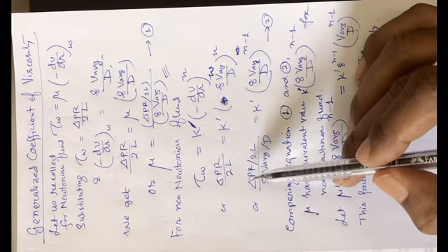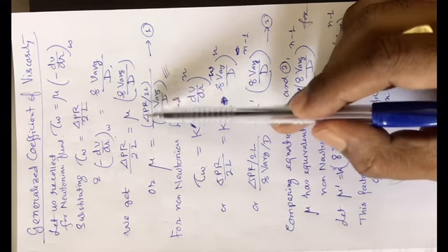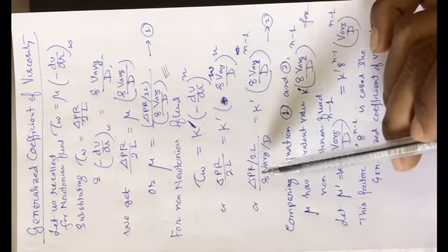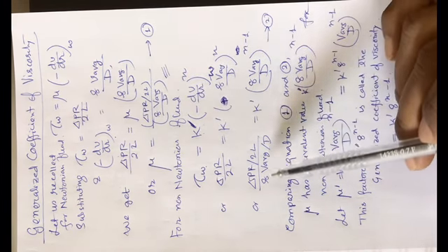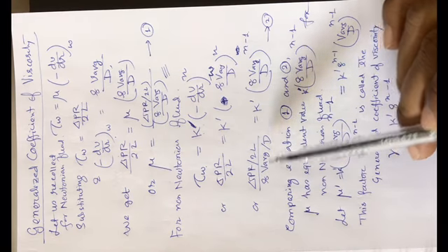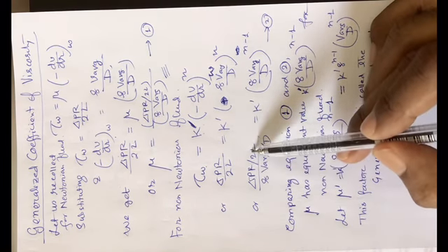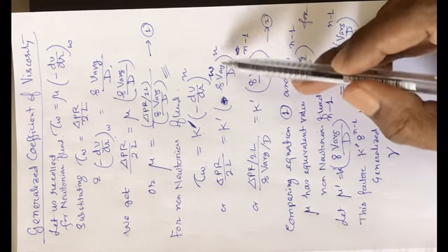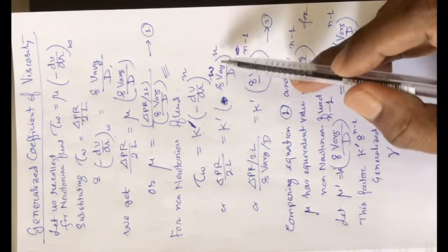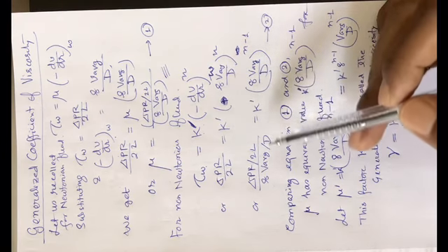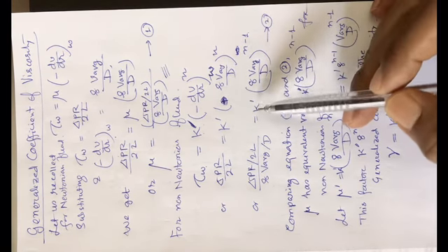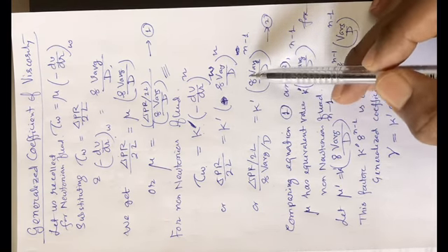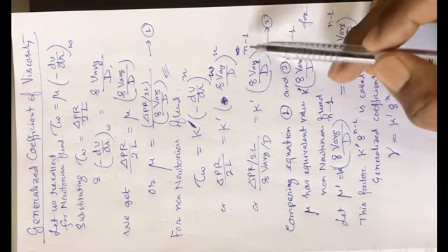Now what we require is this ratio, delta p r by 2l divided by the shear rate at the wall. Since the shear rate term is to the power n, we take out only a factor of one from it, so it becomes n minus 1. So it is k prime into (8 times V average by d) to the power n minus 1.